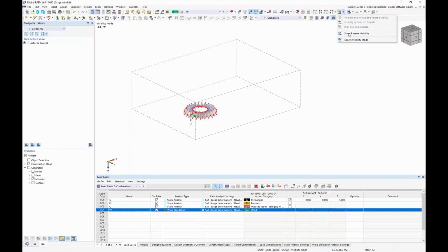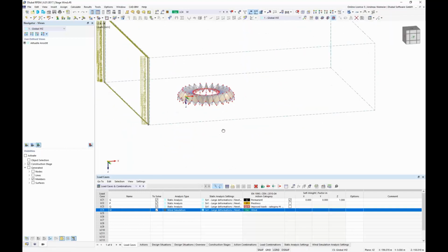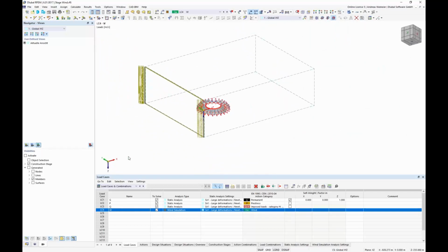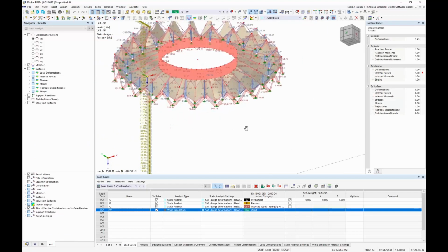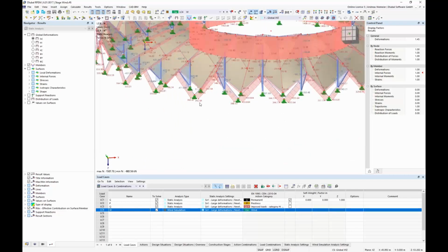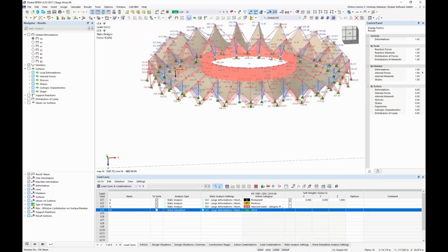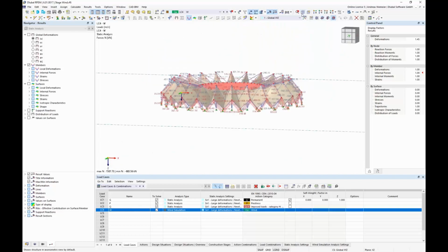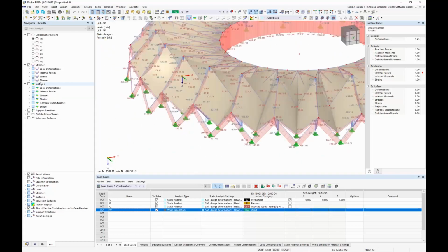tunnel. If we show everything, you see this is the input wind speed like we just saw for 0 degree in X. And now if I activate forces, you see also this is now the structure answer of the wind simulation with the loads what wind simulation calculated on the structure. Here we have, for example, the internal forces, normal axis forces. Maybe only I rotated that we have now, yeah, exactly. And even we get deflections on the structure.